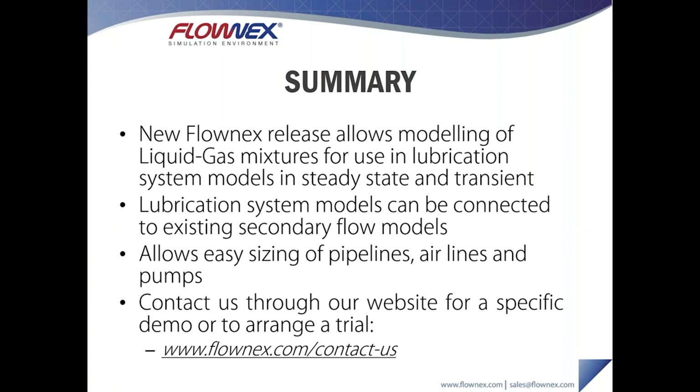In this particular example, I was using the pump components with charts, but realistically, you could just fix the mass flow in a pump component and have Flownex calculate the required pressure rise and volume flow, and then select a relevant pump that matches that performance.